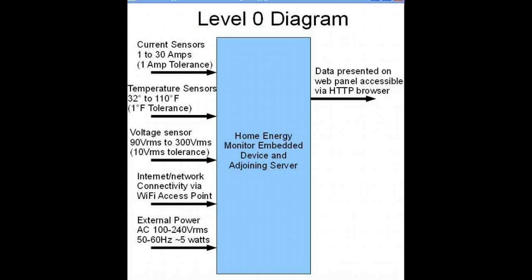One is when you're talking about a variable or some sort of analog input, for example, the current sensor. You got that right. You gave the range over it. A more typical way to discuss tolerance, and this is kind of picky, is one or two ways. One is you give the percent of accuracy. In other words, you would say accurate to within X percent. And that might be 1 or 5%, and basically that's thought of as the full range.